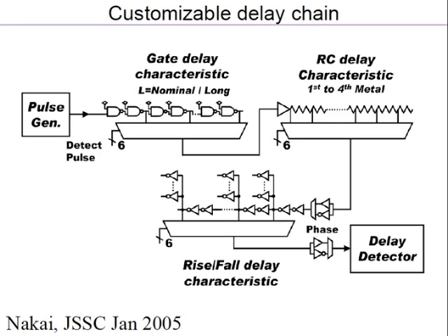The bigger one, measuring the critical path delay is very difficult in the actual circuitry because you don't know where all the, it's like it's all kind of distributed. Here it's a small piece of circuitry you can put next to the controller in a place where you can measure. So what people do is that you can create a critical path model with gates, maybe a mix of gates.